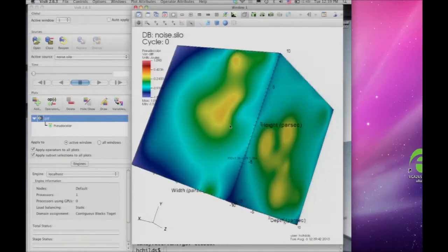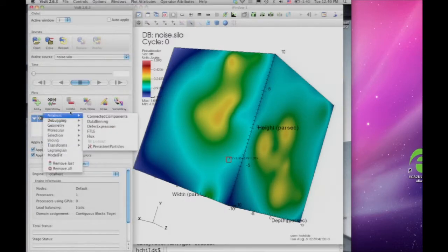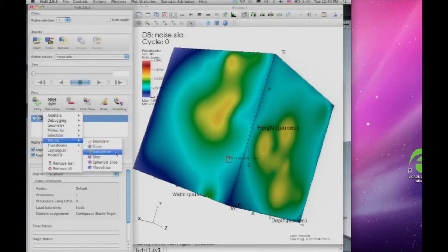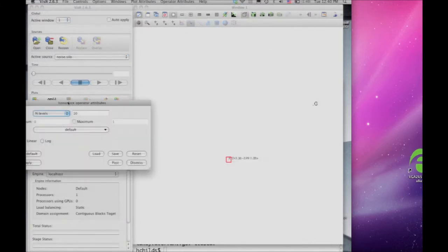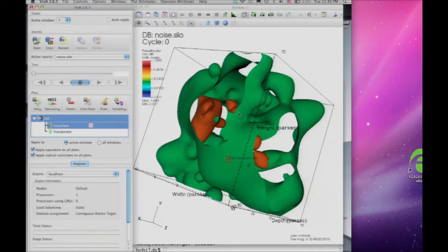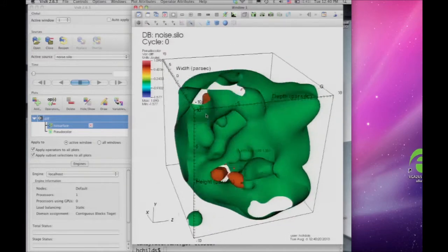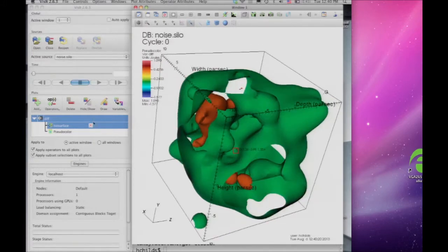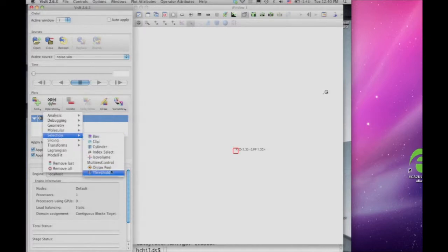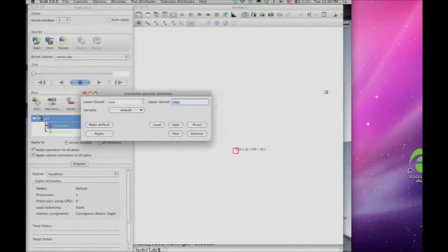Tensors, tensor visualization is really hard. The common way to do tensor visualization is you take a sphere and you deform the sphere by its eigenvectors, and the amount of deformation is its eigenvalues. And I'm just not smart enough to look at that stuff and actually learn something meaningful. I guess if you really train yourself, you can get a lot out of it. What we tend to do is we have some neat things: calculate the effective strain, the effective stress, principal deviatoric strains and stresses. Basically to take these tensors and turn them into vectors and scalars that we can actually understand.